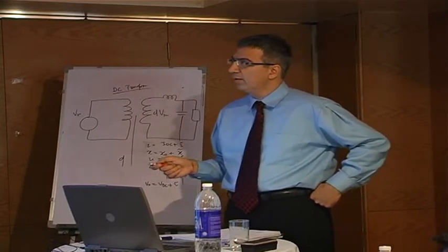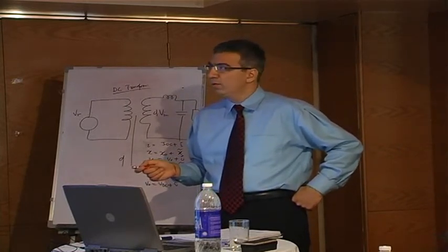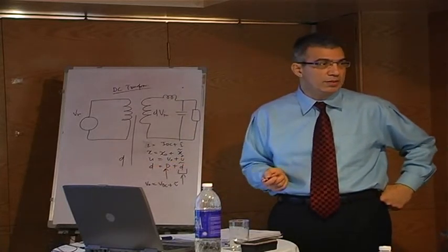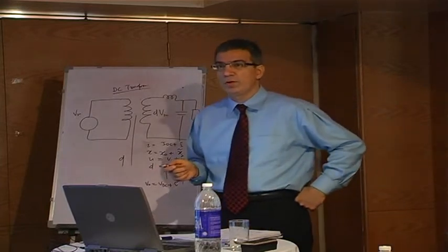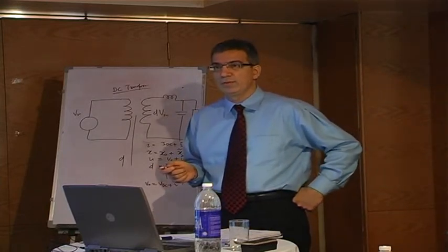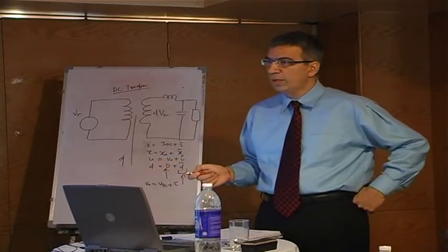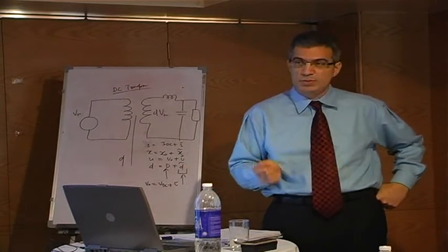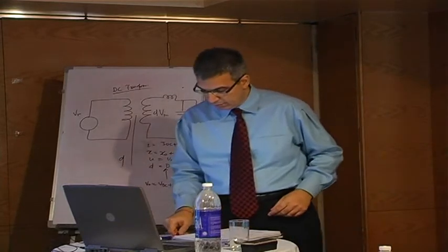But that is the pulse width switch model, which now you can use in just about any topology, and you can have a Bode plot, and that Bode plot is a pretty good starting point for your power supply design. Okay. Right. So with this model, you can quickly do your power supply design, and you can have a Bode plot, and you can have a compensator, and all the good stuff. So now the details of this model.